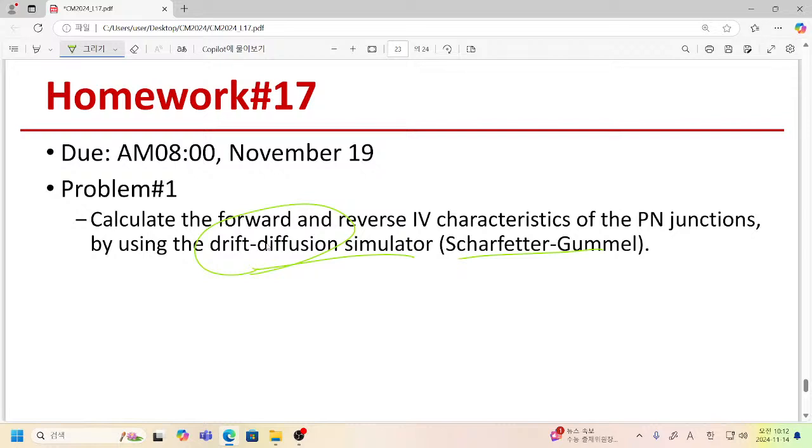Also, the Scharfetter-Gummel scheme and our previous naive scheme give you good comparison data. You have the Scharfetter-Gummel scheme, our previous naive implementation, and the nonlinear Poisson equation. At equilibrium, all 3 implementations at reasonably fine grid should give you the correct result.